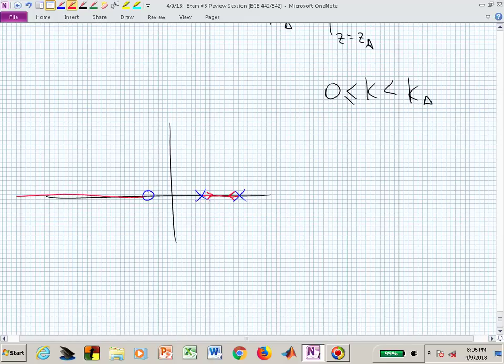How many branches are on that segment to the left of the 0? 2. We have one branch going to the finite zero and one branch marching off to infinity. And now we have to worry about how we connect those two branches. They can't just magically show up. And for this pattern, that's where the circle comes in. The circle is centered at the zero. The radius is the geometric mean between those zero and poles. So if I just quickly eyeball it, this is what it is.